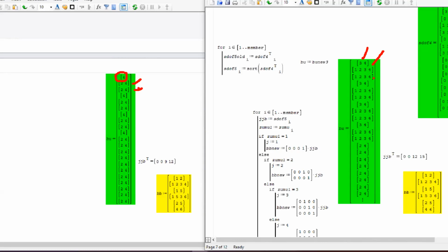As you notice, that changes the behavior of your frame. This is the implication in your S matrix. Here I only need one data on my member 4, but now I need two data because it's already sway. On member 5 I only need two data because no sway.